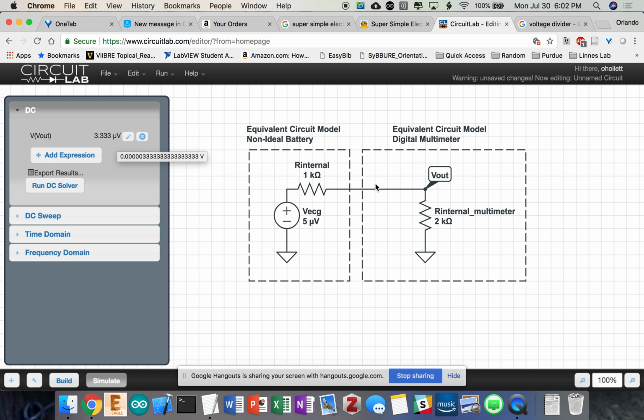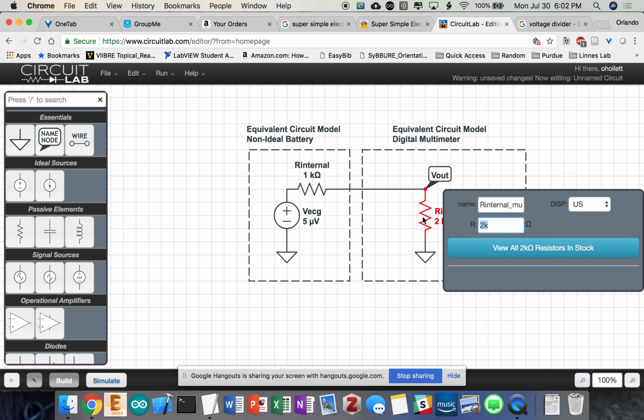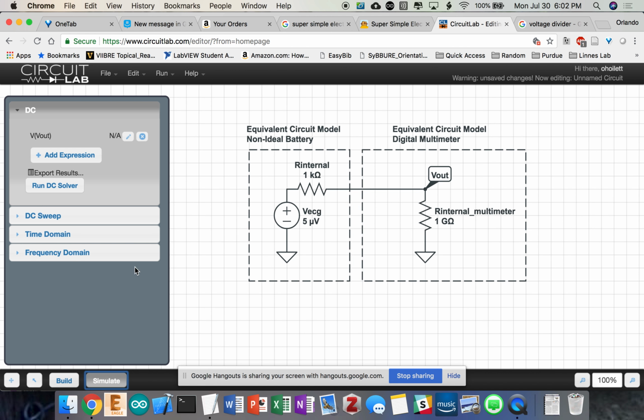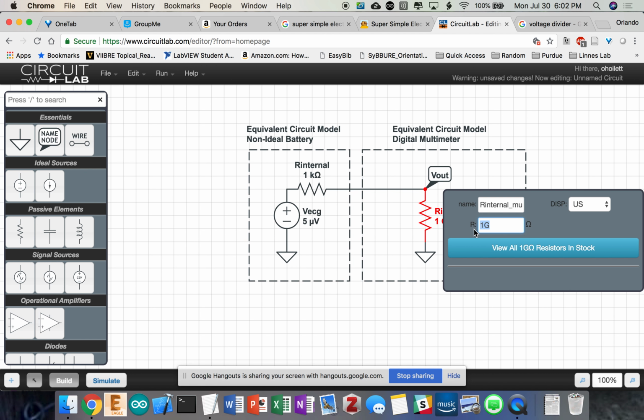So instead, we want systems that have internal resistance, honestly up to giga-ohms. And so that would mean that I'm getting my 5 microamperes passing through. So for that case, instrumentation amplifiers are very, very well known for having high input resistance, meaning that this R internal is just ungodly high.